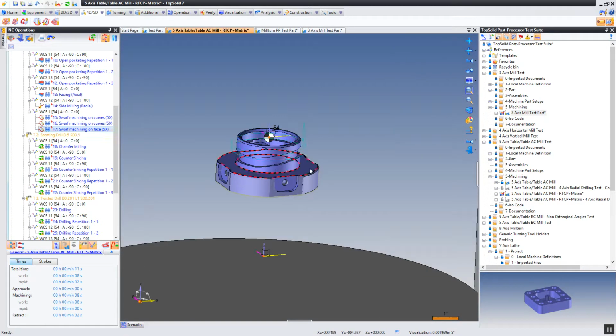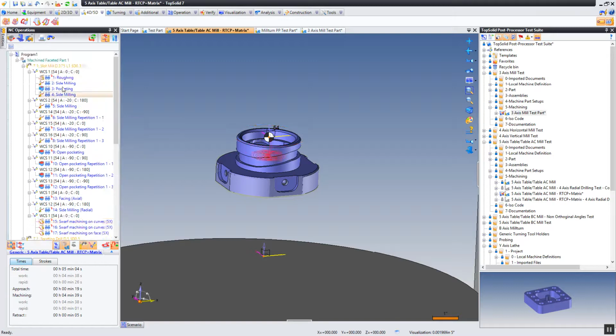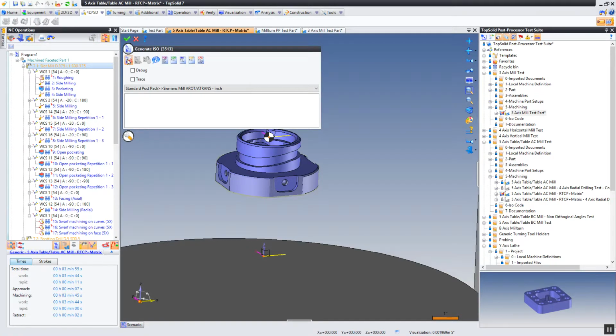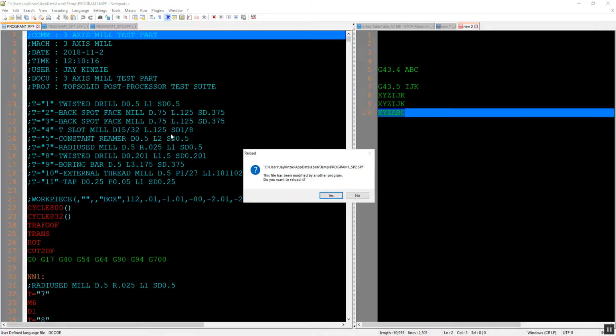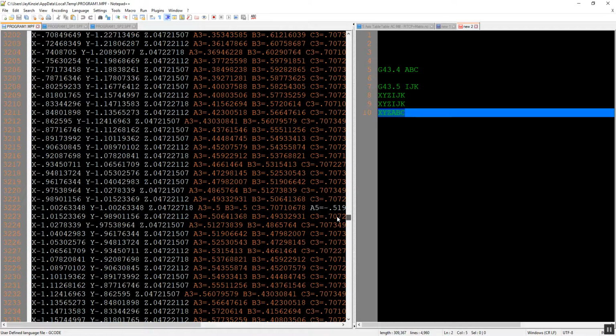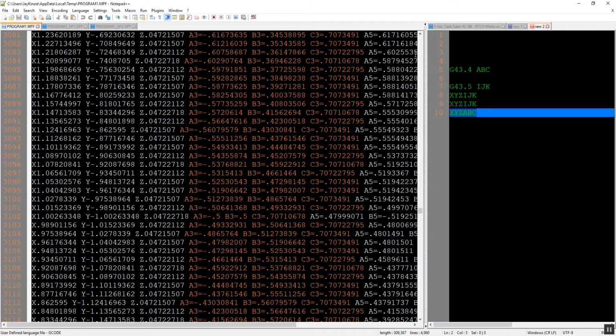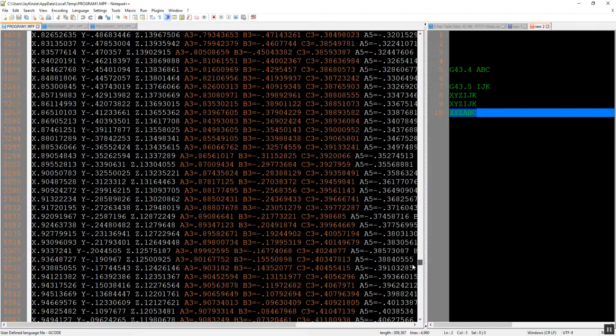Basically, if we asked the rotary axes to move, and the rotary axes have moved, but the tool vector is not moving or hasn't changed, then we know that we're at a singularity, and whatever we're doing is ambiguous, effectively. So with that check, we can actually output code that's regular ABC code, and we don't have to use vectors for that. And this way, the simulation will actually match the code.